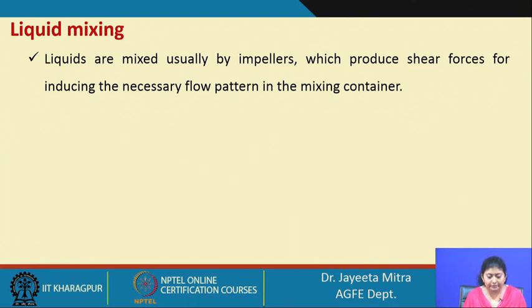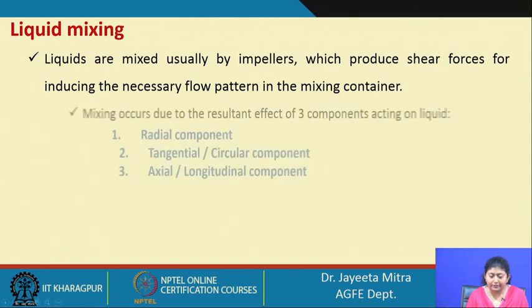Liquids are mixed usually by impellers, which produce shear force for inducing the necessary flow pattern in the mixing container. So, now creating flow is a bit easy in the liquid, but what will be the direction of the flow, that matters many times. Okay. Or if you are not mixing only two liquids, but there is a liquid and solid mixing, then also what kind of flow pattern you are generating, that is important. Therefore, the impellers produce the shear forces for inducing the necessary flow pattern in the mixing container.